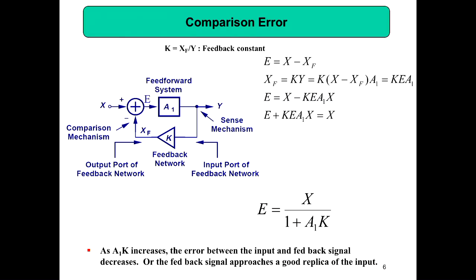You may get some glitch. You know what I meant? And then that will go as the input to the amplifier. So you don't want that to happen. So in order to make your feedback system very good, this signal and this signal, xf, should be the same in the sense of shape, not amplitude. So this xf should be a replica of the input signal. Otherwise what will happen is your error is x minus xf. So if both are following the same trend, the error is going as the input, so that trend is followed to the amplifier. But if it is not, you may get distortions.